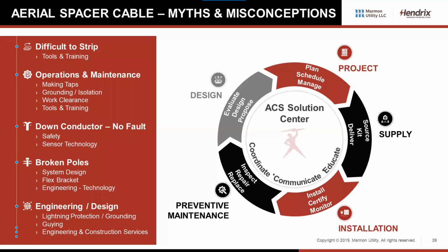It usually comes down to having the right stripping tools that are designed specifically for spacer cable, how to make taps, grounding the conductor, work clearances, and all that other stuff. We've got the ability to do the training either remotely or on site. We've got field service guys that literally travel all over the world helping clients install spacer cable, because it is a little bit different than installing traditional bare wire.